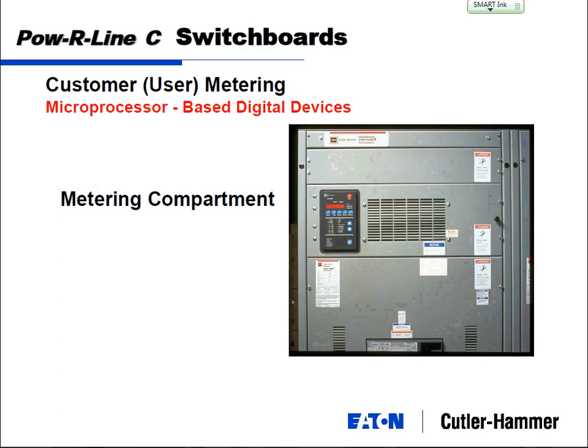Now what that allows them to do is you can always verify the utility bill with whatever billing parameters you're getting billed at. Sometimes it's strictly kW, kilowatt hours. Sometimes they put a demand charge. They want to see when your peak usage is. And sometimes they'll put a power factor penalty charge. And all these can be factors in the utility bill.